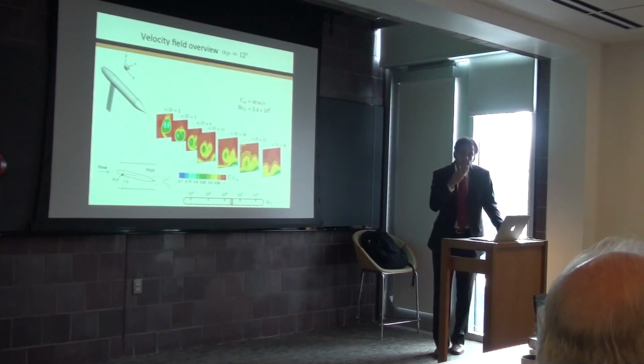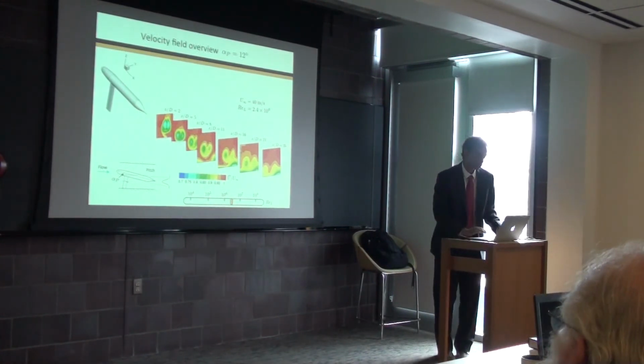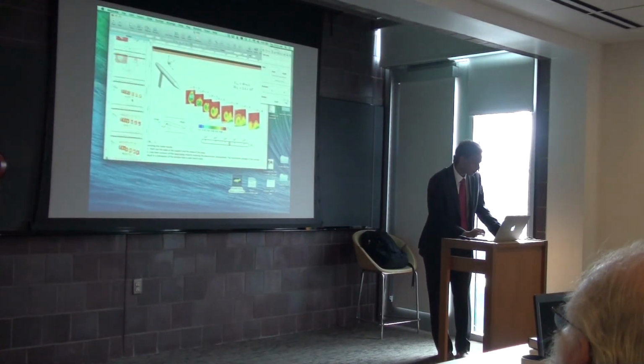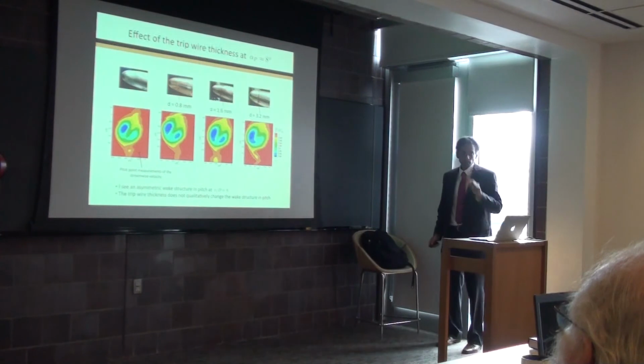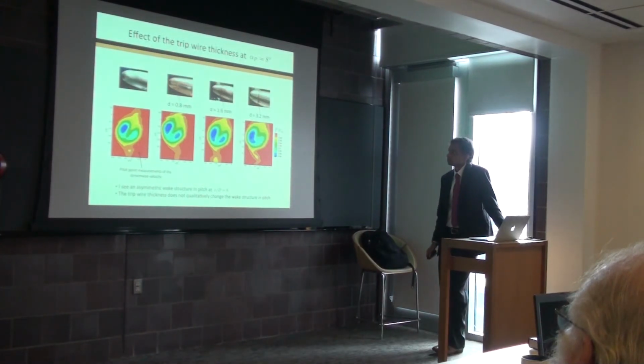Okay, I just have one question. Came back to the slide where you have the different size tripwires. There's something interesting that struck me. If you look at the two vortices, the stronger one's relatively robust to the different size tripwires, but the weaker one does have some variation. Any reason for that, or comment, or is it just a computational matching thing?